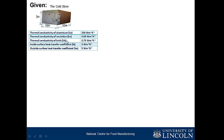The reason why I use Kn here is because I know I'll be using i as a subscript here, so it doesn't really matter. You can call this one hsi, but I just want to make it simple. Hi, then I use the second letter of insulation for this. The most important thing is wherever you're supposed to use the thermal conductivity of insulation, you use the value of 0.04. That's the most important thing. And then the outside heat transfer coefficient is given to us as 5.